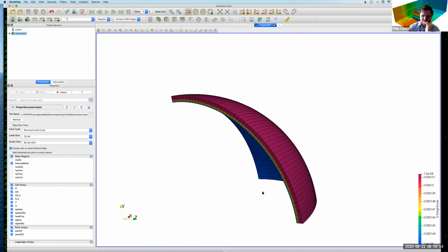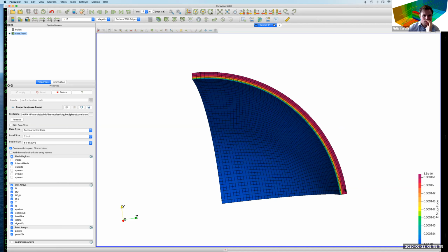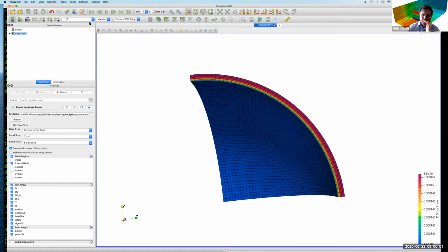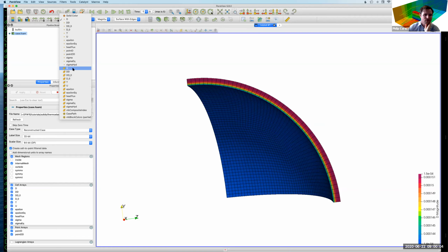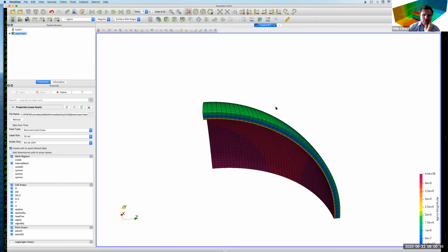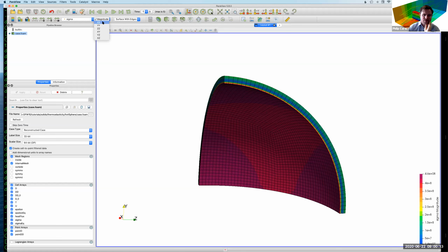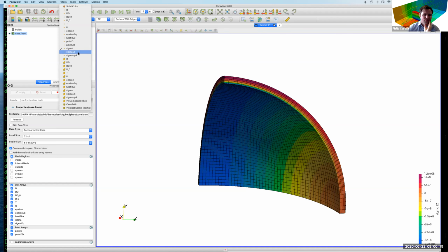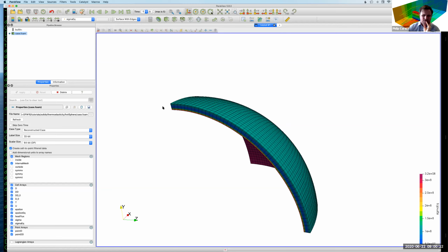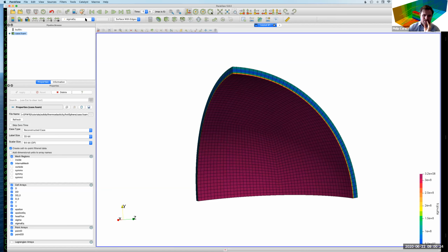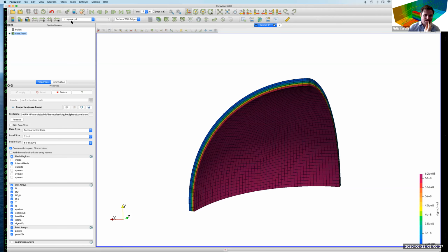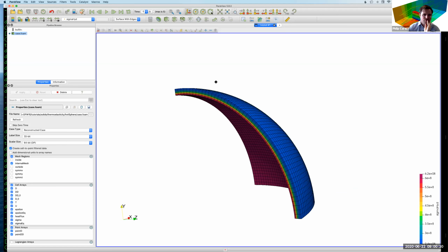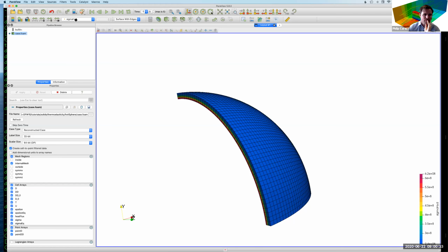If you look at the displacement field, this is the magnitude. It's greater movement on the outside than the inside. But the solver will also print out a number of other fields. So sigma is your stress tensor. This is a symmetric tensor, so you've got all your components, if you want to look at them. And you've got sigma EQ, or sigma equivalent. This is the von Mises stress. You've got the hydrostatic stress as well, sigma Hyd. This is like pressure in the fluid, except it's the negative of it.